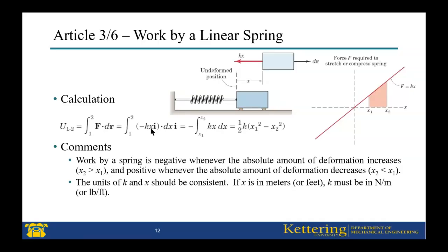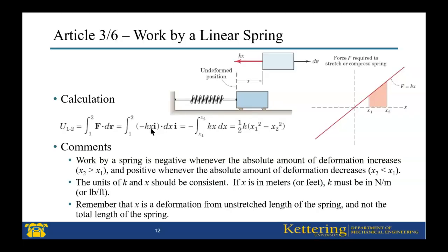Then, the units of K and X should be consistent. If X is in meters, K also should be in Newton per meter. If X is in feet, K should be in pound per foot. Make sure those are consistent.